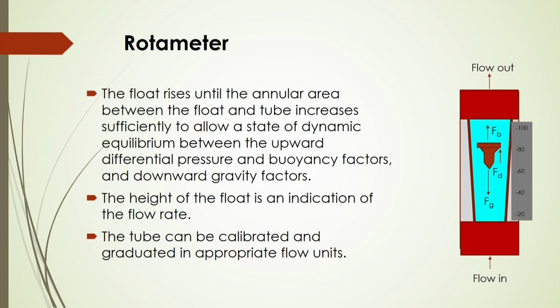If you get these 2, 3, 4 or 5 points based on the known flow rate, and the scale of the flow meter given by this rotameter, then you can draw a graph like this. The known flow rate is the actual q, and the other axis is q rotameter, the flow rate given by the rotameter, and then you can get this type of data.